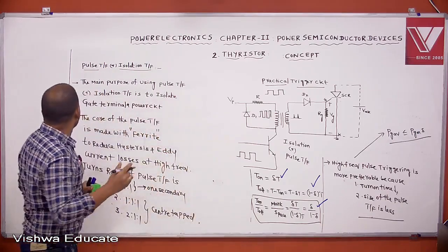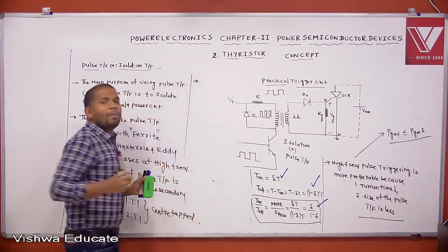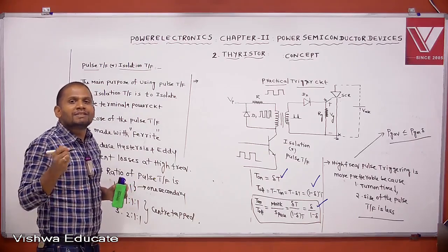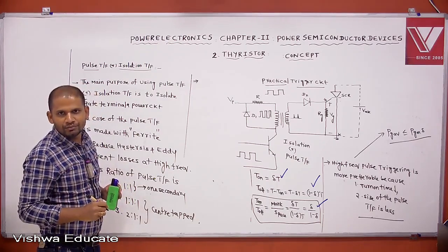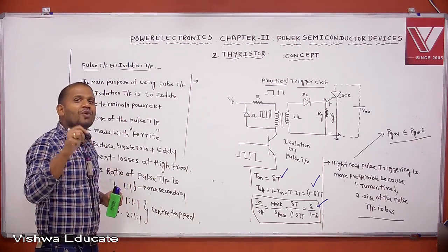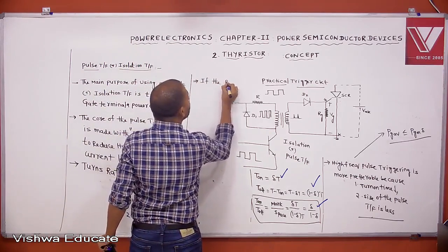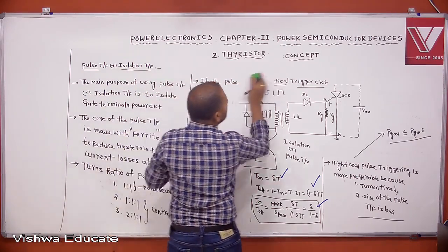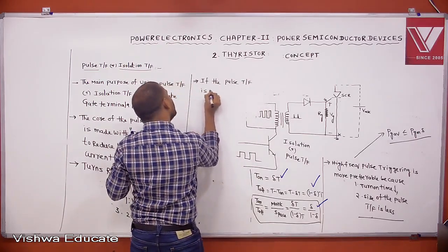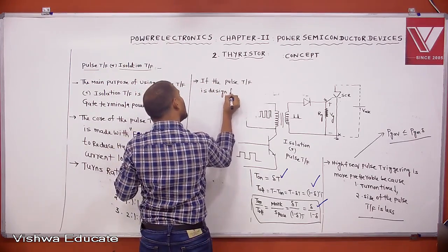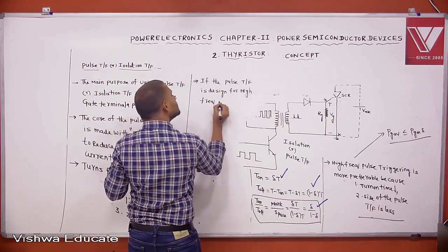Another point to remember with respect to the pulse transformer: it must be designed for high frequency, because then the size will be reduced. Understood? If the pulse transformer is designed for high frequency, then the size is reduced.